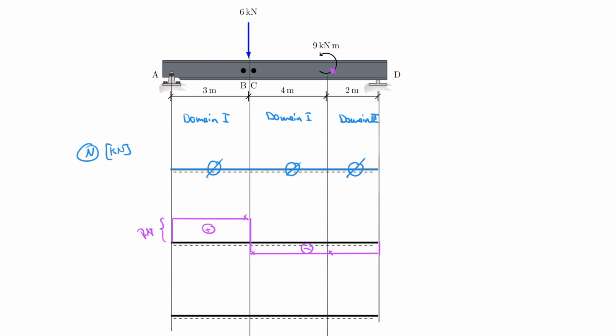And notice one important thing that I will explain to you after I completed my diagram here. Number one, I forgot to indicate that it's the shear force and that it's also in kilonewton. But really what I want to put your attention to is that there's a moment here, a concentrated moment, which you see that right, there's no influence on the shear force diagram.